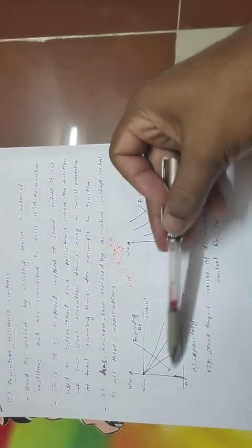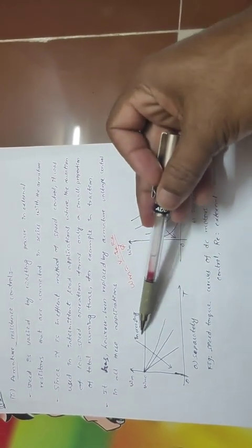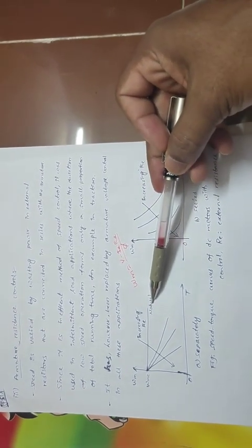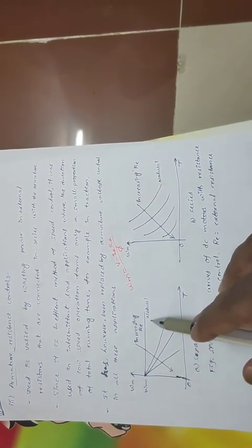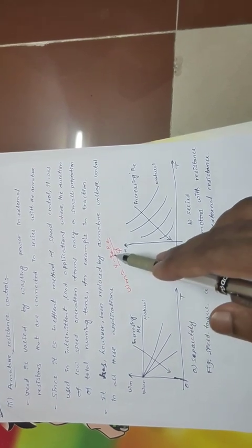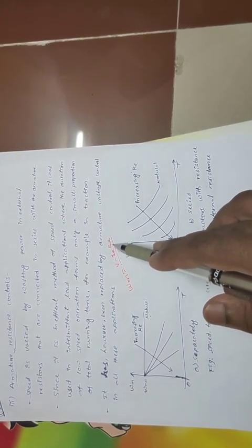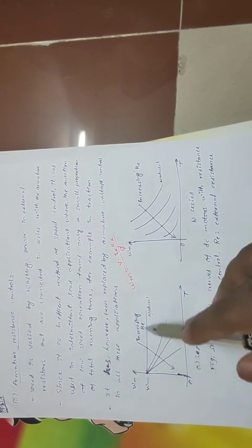The natural speed torque characteristics are the same. Again, in the separately excited motor, this is the constant characteristic, the natural characteristic. Like I told you, in the separately excited motor with armature voltage control method, there is a slight droop in the characteristics, because by neglecting the armature resistance drop, your characteristics will be constant.